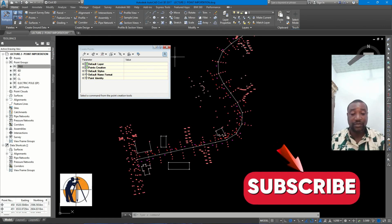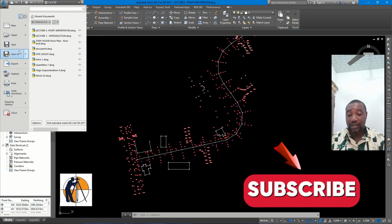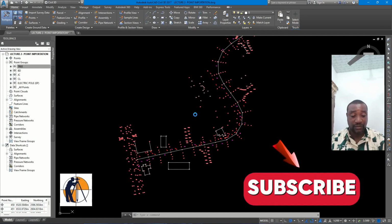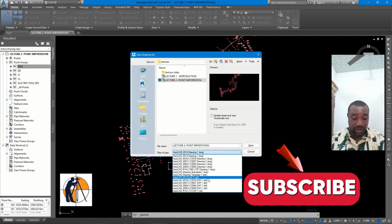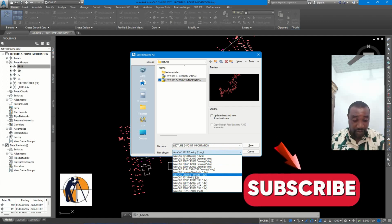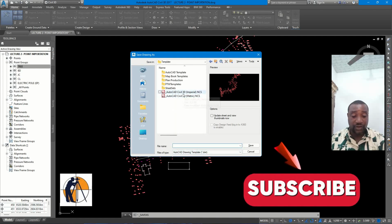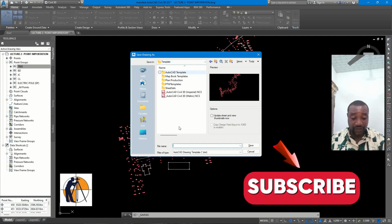Now, if we want to save it to a template, it's just as easy. We just go to the format and click save as. Save as, you will select other format. You come down to this point and select drawing template. This is it. You indicate the position. These are other templates that are in there, so it just goes straight to your template saving position folder. So I will save it there.